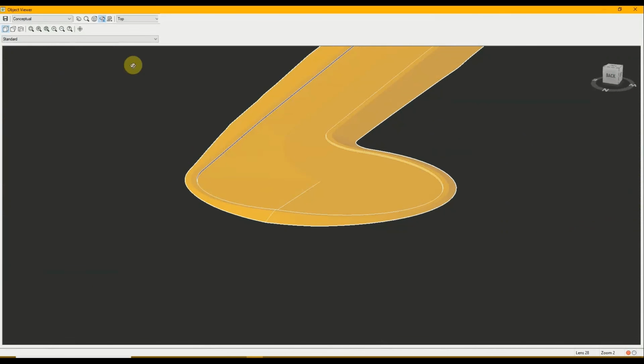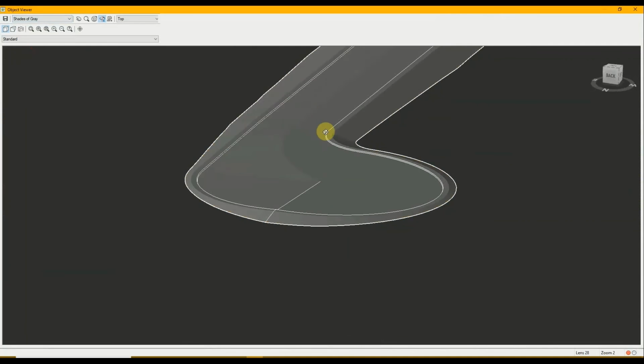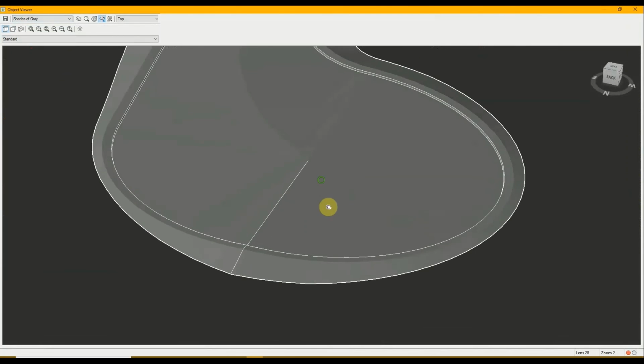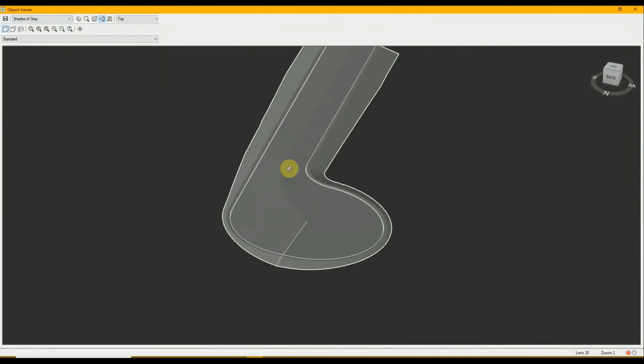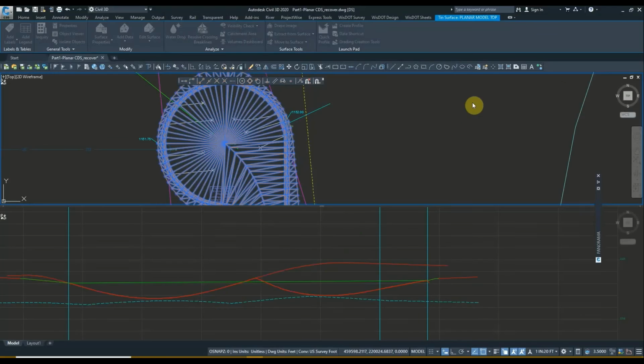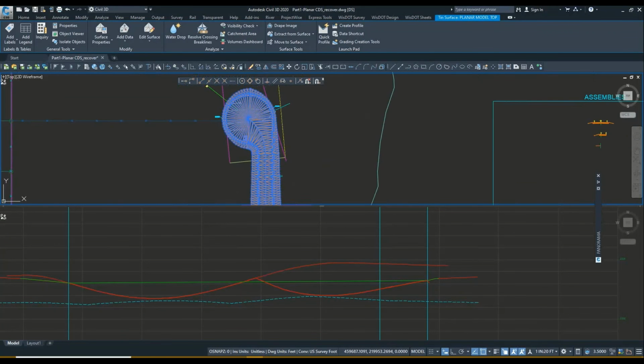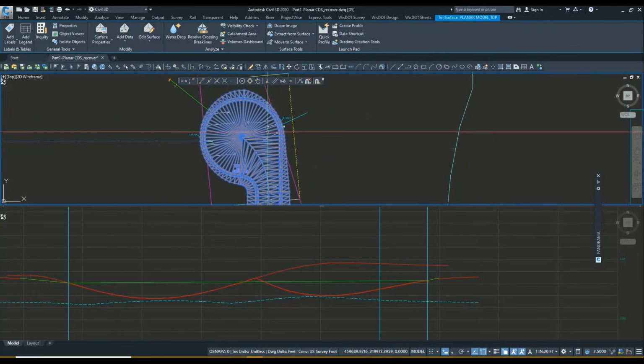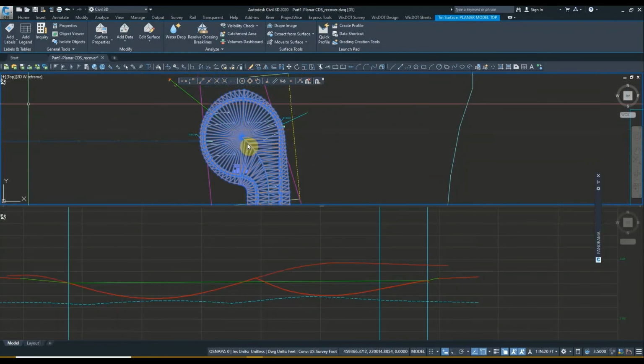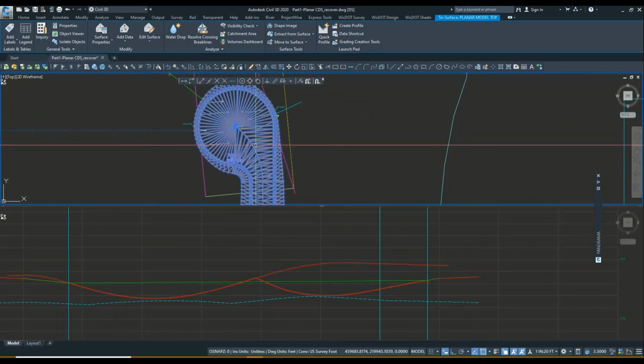You can see we have a faint crown. Maybe with this one you can see it a little bit better. As you can see, we now have a crown with this area draining this way. And so now we can control exactly where the water goes for a crown cul-de-sac, and we can hit a specific inlet at a specific elevation.